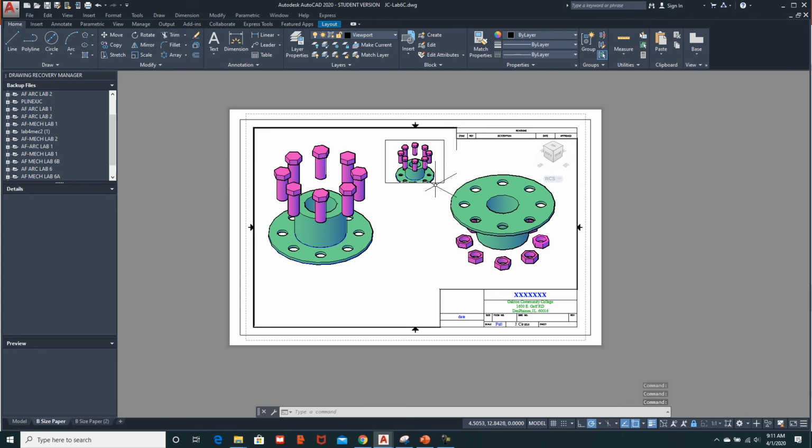click outside of it, and you can see it has difficulty when layers are overlapping. And so I just kind of did this way, but I was hoping that I would be able to grab the viewport itself and make it a little bit bigger, and it's giving me some difficulty. And so if I double click out into Paperspace, now I can get it. And so viewports are created in Paperspace, and so when you're in another viewport like this, it's called floating model space. And so it's the model space, but it floats in the viewport, floating here, floating here.